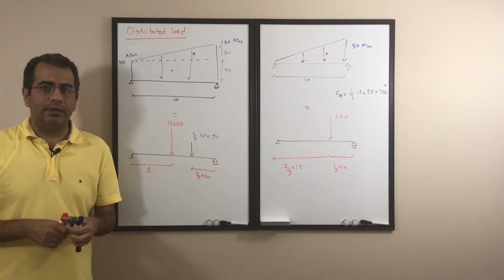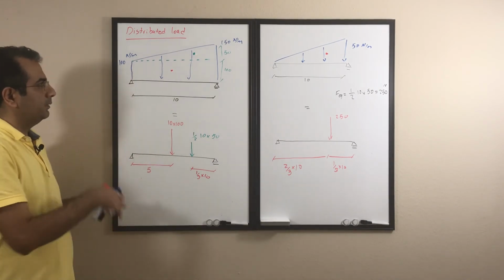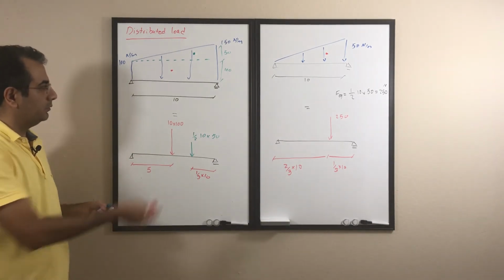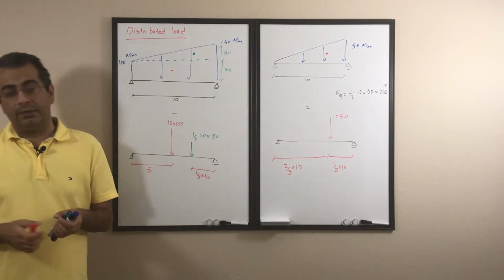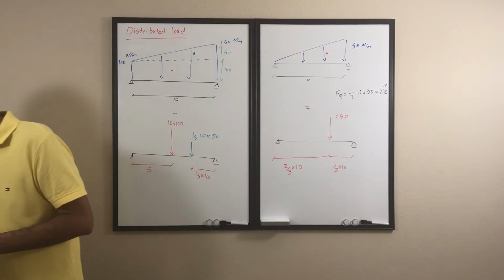So anytime that we have a distributed load, just go ahead and replace the distributed load with one or a series of single forces, and then start to work with those forces.